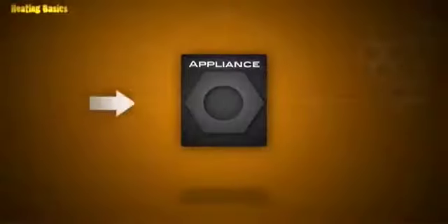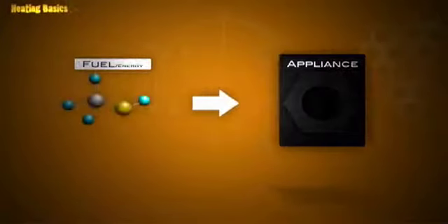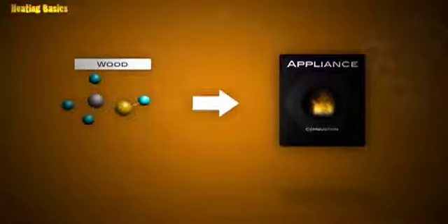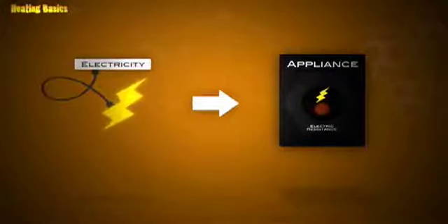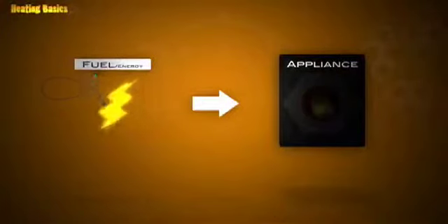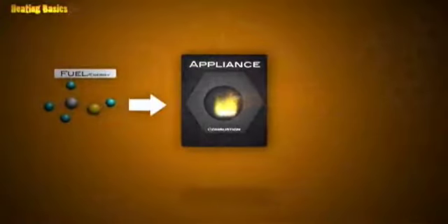Based on the type of process used, there are a number of energy or fuel sources that may be used. For example, the combustion process may use natural gas, propane, coal, fuel oil, or wood. The electric resistance method utilizes electricity as the source of energy, and through the use of highly resistive elements, it is able to produce heat. The heat pump utilizes electricity to power a motor, which is used to move energy from one location to another, utilizing the refrigeration cycle.